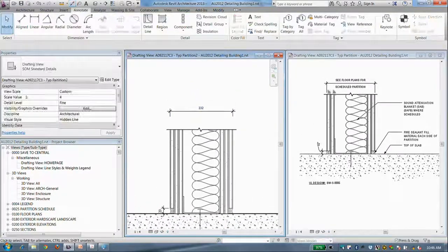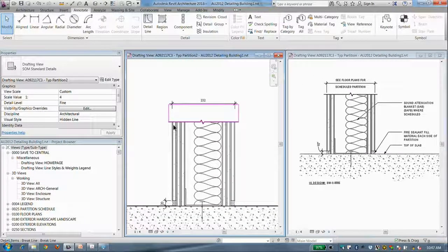And notice that on the original detail, they don't actually have the value because the width of the wall is really dependent on the different types of metal studs being used and in other settings. It could be a rated wall for whatever purpose, acoustics or fire rating, and that's the important part. The actual width is kind of dependent on other factors. Also, the height of the wall may get a bigger stud and so forth, and therefore require a different width. So we organize it this way.